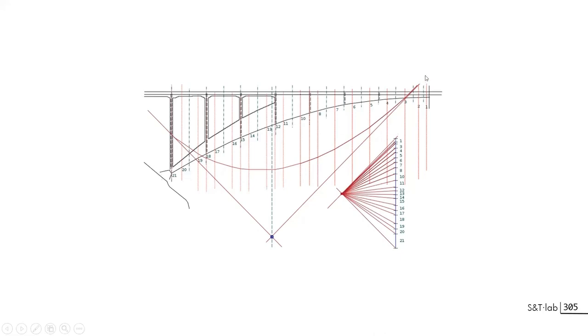What you know is that the system is symmetrical. Actually, it's not symmetrical, but it's quite similar to symmetrical, and hence the horizontal line here. We can demonstrate this is equivalent. And you know that the line of action starting from the middle will be horizontal. It has to be in equilibrium with the line of action of the resultant force and also with the line that will come from the support.